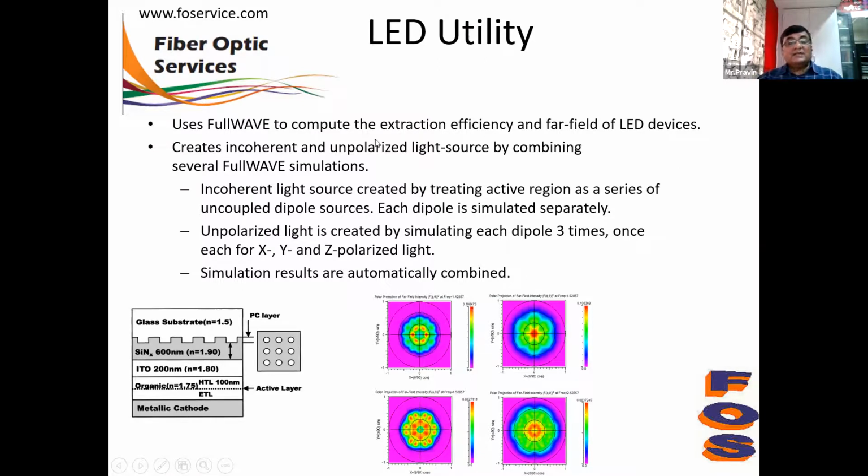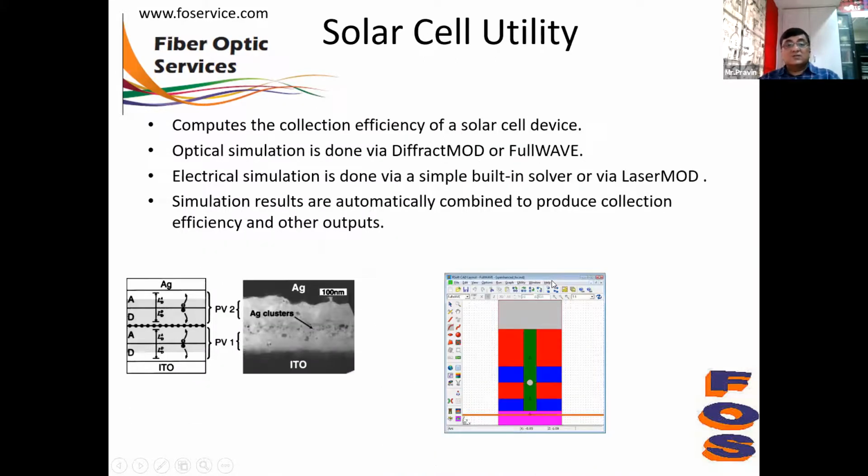The LED utilities are for computing the extraction efficiency. As I have mentioned earlier, the utilities use the optical calculations from the main simulation engine. In the case of the LED utility, it uses full wave for computing the far field, and then it will find the various plots of the LED cross-section structure.